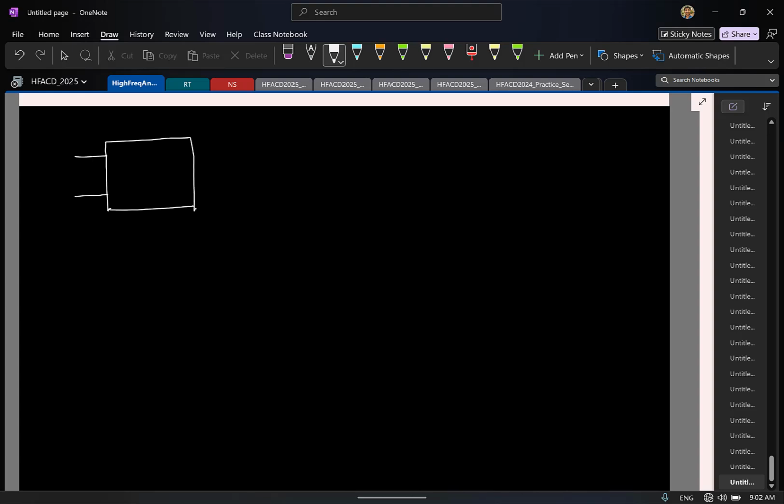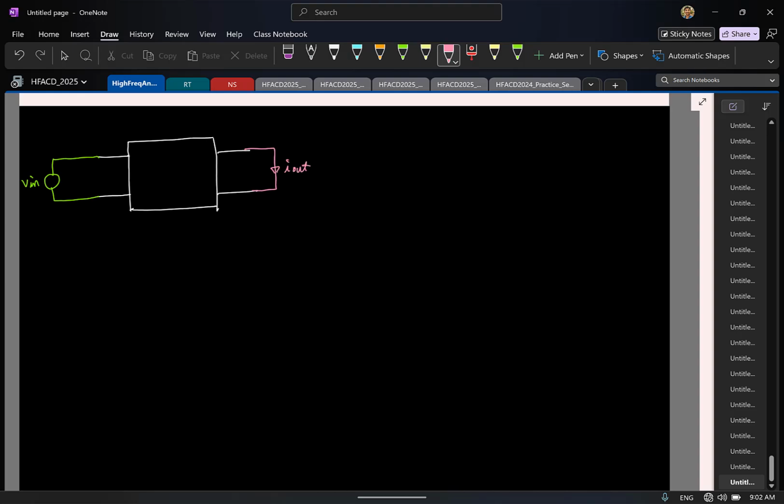and here you connect the input, and let's say at the output you look at the output voltage, or let us say you are interested in the short circuit current. For example, I'll take a short circuit current. Ideally, you expect only the input to appear at the output, but now you'll have noise sources. So let us say I have multiple noise current sources in my network. Now we'll have contribution from all of these noise current sources to the output.